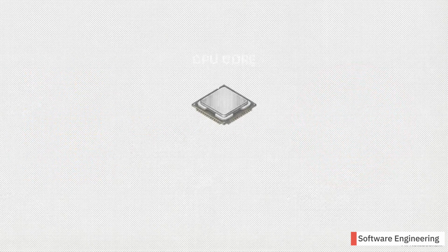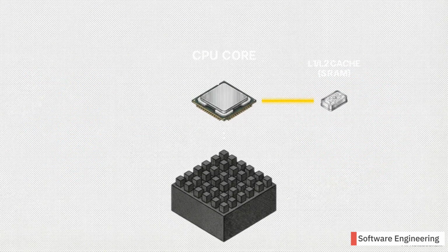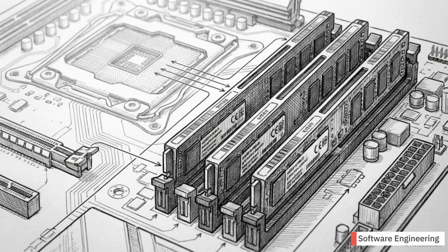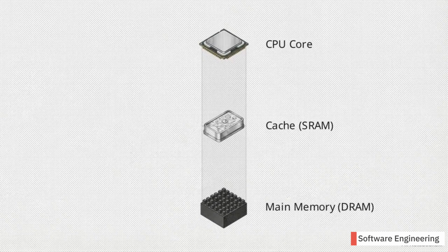Combining these 2 different hardware paradigms explains the modern computing landscape. SRAM's fast, single-level design earns it placement directly onto the processor chip as cache. DRAM's dense, multiplexed one-transistor design banishes it to the motherboard as vast external main memory. During execution, the system must constantly predict and pull bulk data from the slow DRAM, staging it in the fast SRAM cache for the CPU to process.